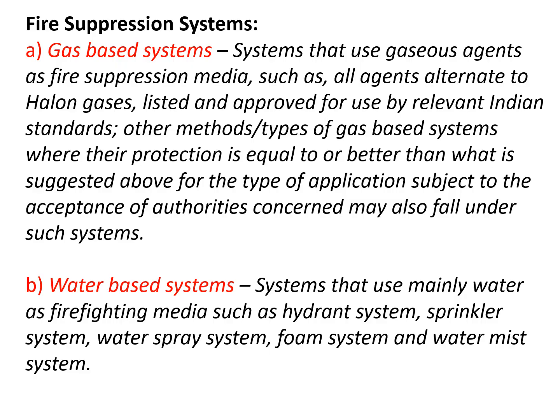Second category is water-based systems. Systems that use mainly water as firefighting extinguisher, such as hydrant system, sprinkler system, water spray system, foam system, and water mist system.